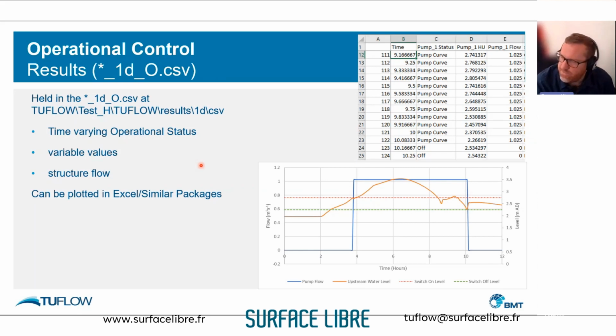Yeah, I think you should be able to do something along those lines using scenarios, events, and variables. So you can have your base TOC file, and then you might just say if scenario equals calibration event 1, read this TUFLOW operational control file instead. I think that would depend on the specifics, but I'm pretty sure you'd be able to do something with scenario logic.